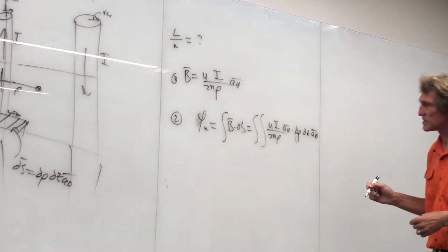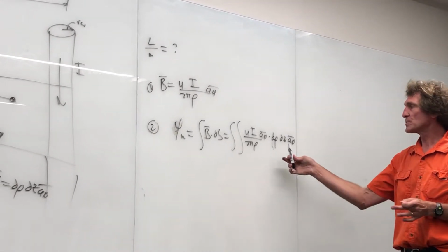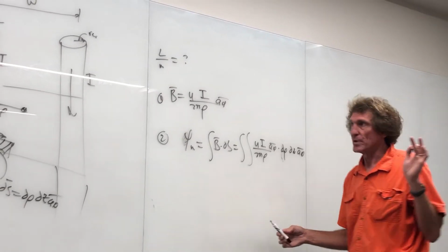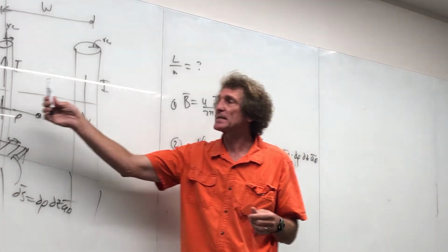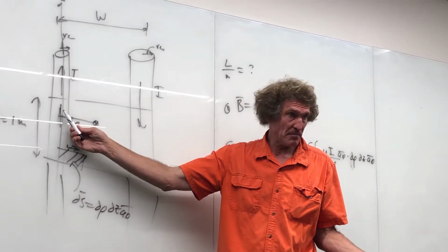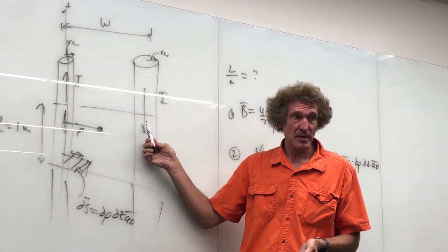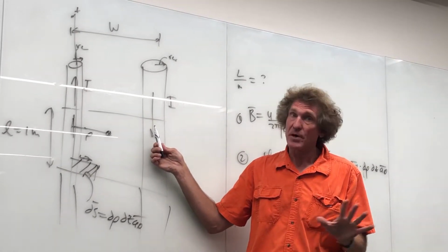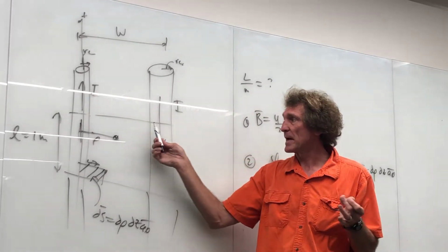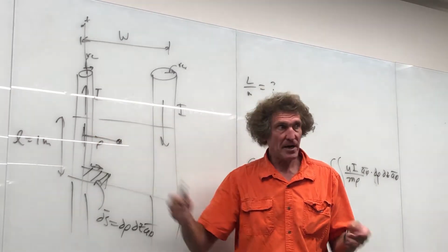Now, this is important. This is where people mess this problem up. Where does rho go from? I'm going to make a comment here. We don't care about the internal inductance per meter of the wires. We know that. This one is mu 0 over 8 pi, right? We're going to add that in at the end, per meter. Right, we're going to get there. But we only care about the inductance associated with the magnetic flux between here and here. So where do we start the integral at?